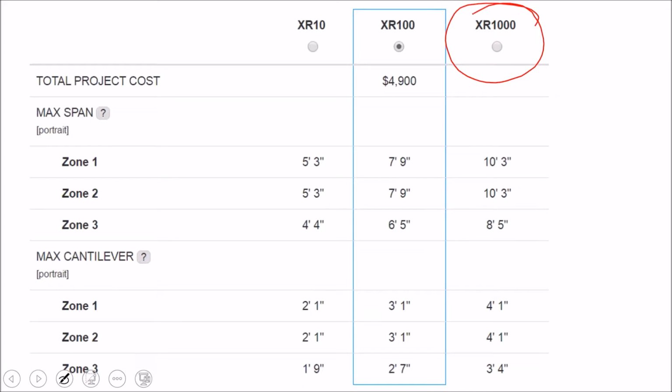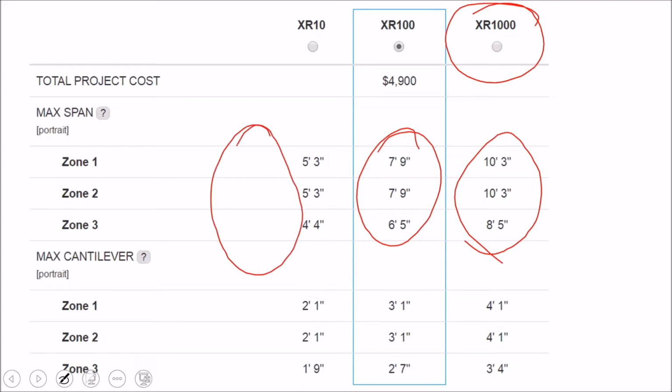My structural engineer is not telling me I can do 8 foot on center or 10 foot on center. In fact, my structural engineer is not telling me to go 7 foot on center or 6 foot on center. But for this particular metal rooftop, which is a less expensive, weaker metal roof, my structural engineer is actually telling me I need to go 2 foot on center rather than anything greater than that. And the sales rep goes, well, what are you talking about? I've never heard of a 2 foot on center attachment point.